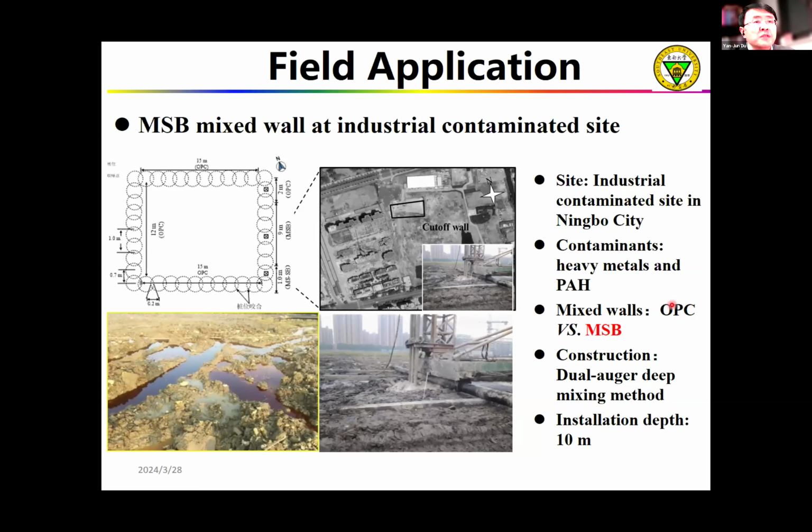We used 2 types of backfill material. One is MSB, another is OPC, which is commonly used in the China market. The construction method is the dual auger deep mixing method.